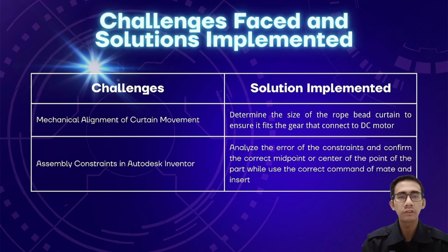As for the challenges during my part, the first is during the assembly constraints. To solve it, I analyzed the error of the constraints, confirmed the correct midpoint or center part, and used the correct mate and insert commands.